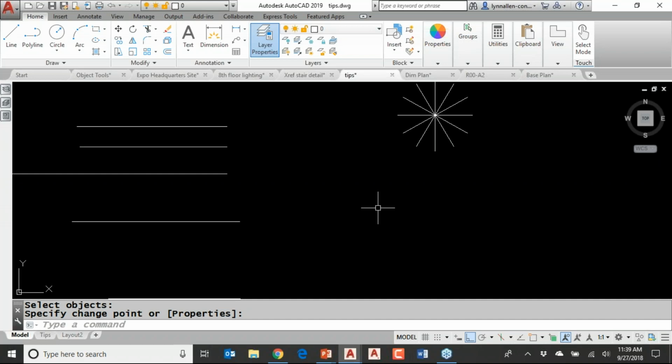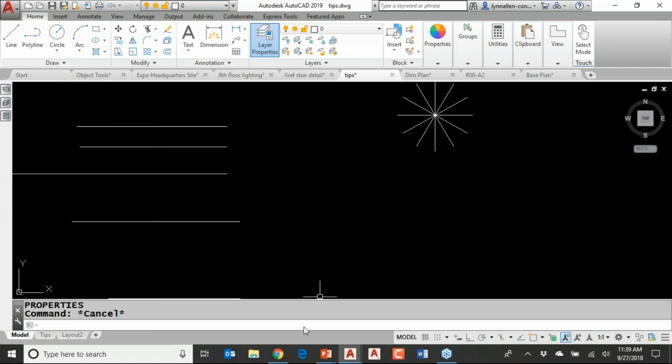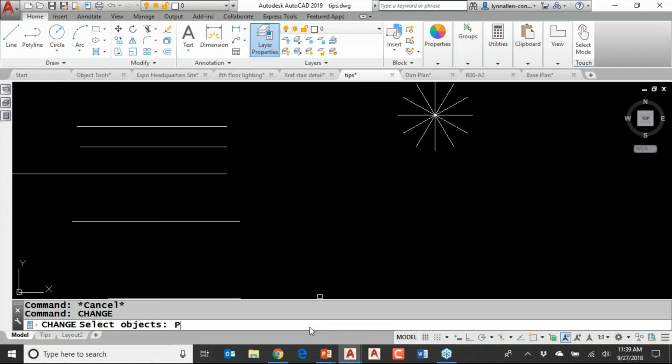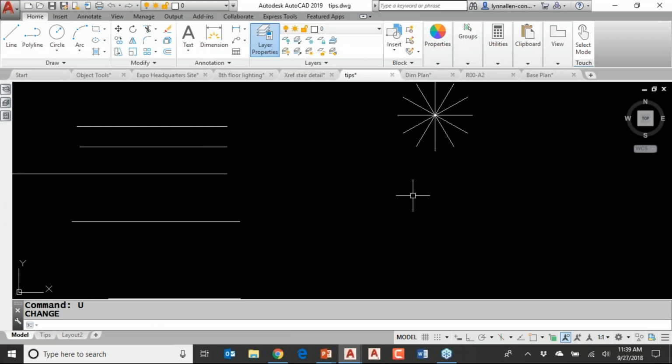Now, why, Lynn, did you have the ortho on? Let me show you. I'm going to turn it off. Let's go back into the change command. Used to be that CH did change, but it doesn't anymore. Let's do P for previous. And now I'm going to pick a point out in space. Check that out. That's probably not what you wanted. I don't know, maybe it is what you wanted. Probably not. Consequently, you more than likely want to have your ortho on. All things for you to think about. All right, so that's the change command.